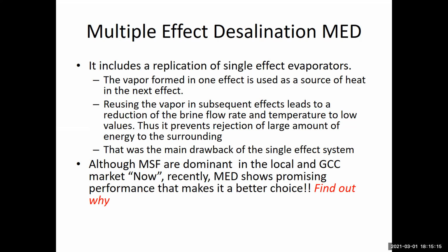So what I want you to remember from here is, for an MED system, theoretically speaking, the performance ratio is directly proportional to the number of effects. You need a higher performance ratio, increase the number of effects.